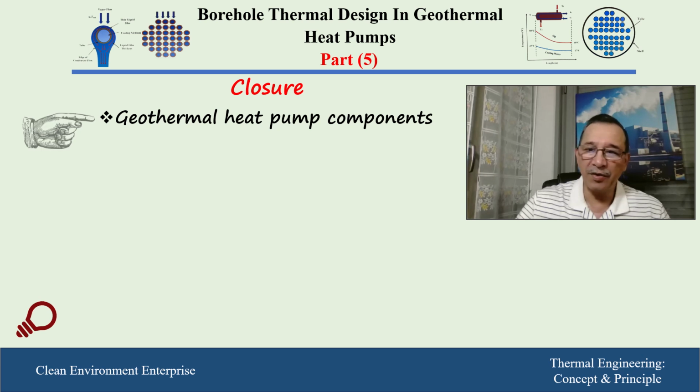We passed through the geothermal heat pump components, the underground part, which represents the borehole, and the other parts which are on-ground parts, which include the compressor, expansion valve, and either the evaporator or the condenser for the direct geothermal borehole, where the fluid passes through the tube, the U-tube, and is the same fluid which is circulated in the heat pump itself.